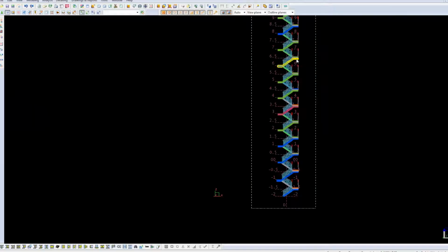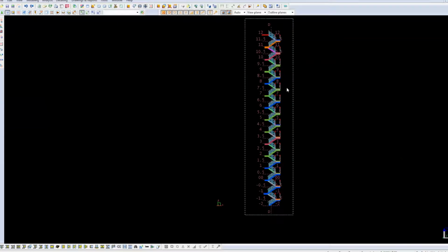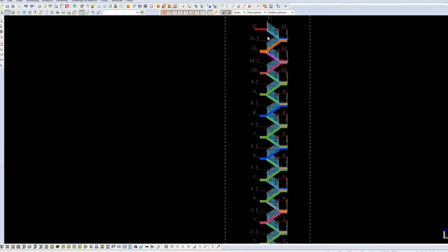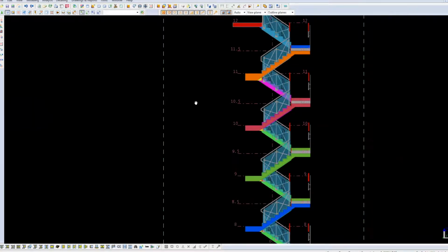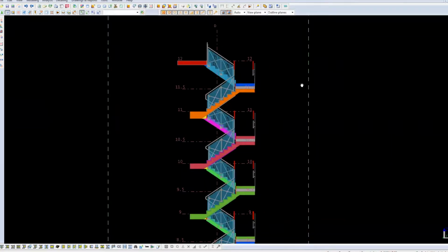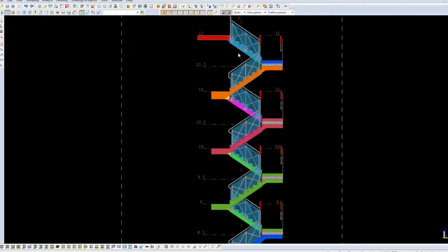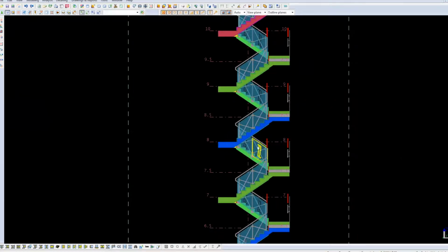I use those sheets for this job, and like I said, there were 5 of these staircases with 20 flights in each. I measured all 5 staircases over a couple of days, and by doing that justification, using a couple of those big summary sheets, I could work out roughly what common angles were. Now you'll see that these stair flights are in different colours, and they represent angles that match each other.